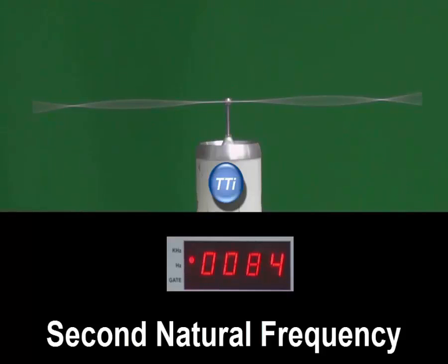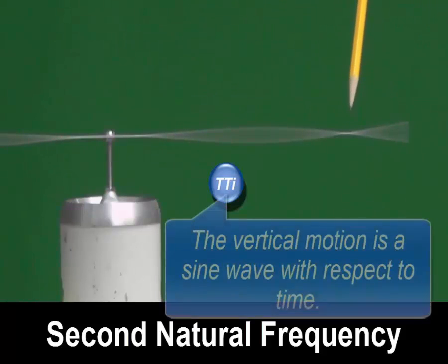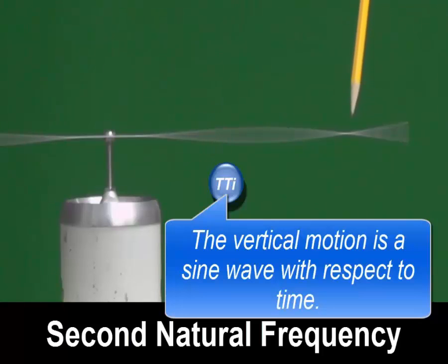There's some interesting things happening now. The middle, remember, is still expected to be zero displacement and zero slope for the boundary conditions, but now we have something happening right here. We can see a node, a point of no displacement. The beam here is moving up and down as a sine wave. The beam here is moving up and down as a sine wave. But at this point here, we have no displacement.